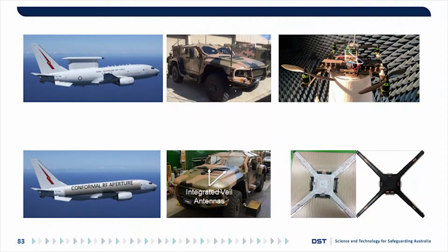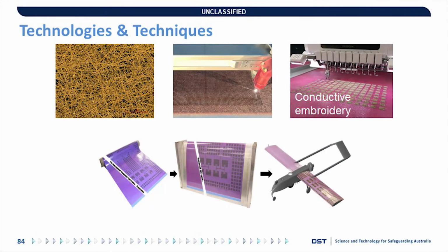So in that example on the right, that's what we made for the Halo project, which we've just spoken about. The way we do this is, one method would be to coat a carbon veil with copper and then etch away any regions where you don't want conductive material, and then you would carefully lay that onto a fiberglass piece. Or you can sew in copper into a fiberglass piece in the places where you do want the conductive material. And in both cases, you then have a fiberglass piece which you can lay up in the same manner that you would any other fiberglass piece. And it doesn't affect the cure cycles at all. So it's very easy to work with in that sense, and it conforms to whatever surface you put it on.